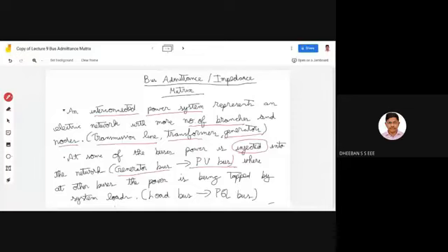In a maze, there will be a point of entry and a point of exit. Similar to that, over the complex interconnected power system network, there will be a point at which the power can be injected, as well as a point at which the power can be tapped out. The point where the power can be tapped out is a PQ bus or a load bus. Generally, the load bus carries an enormous amount of load, and the PV bus will have the power injection tools like your generators and condensers.